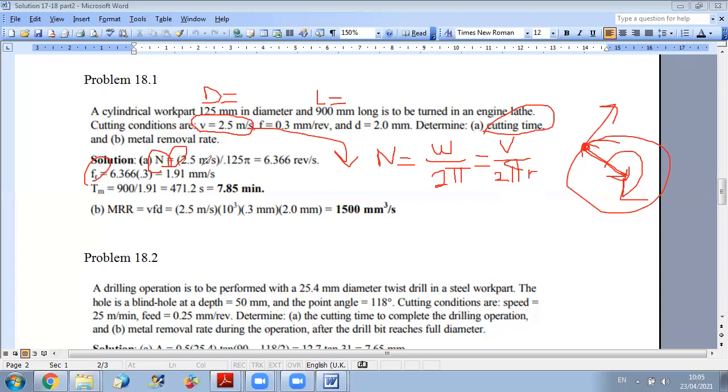Just we should pay attention to units. In case we want to obtain the value per second, then the time unit of velocity will be per second. And concerning the meters, if you use meter per second for velocity, then you should use meters for the diameter also, because you have to simplify the length units, and then you will get revolution per unit time.